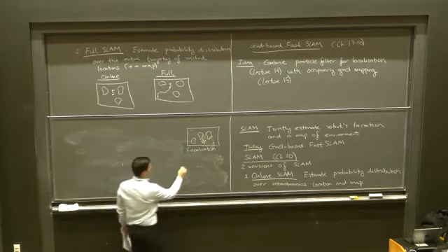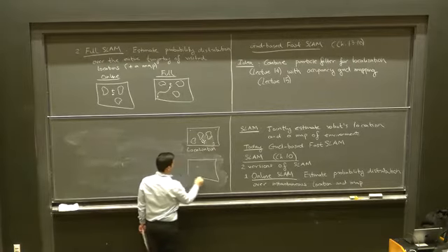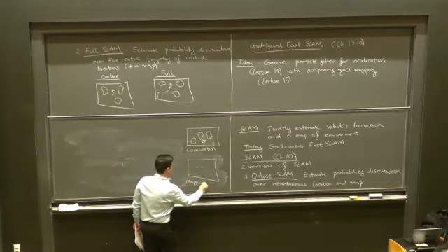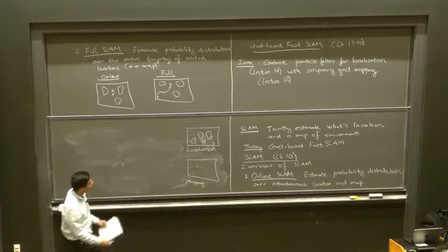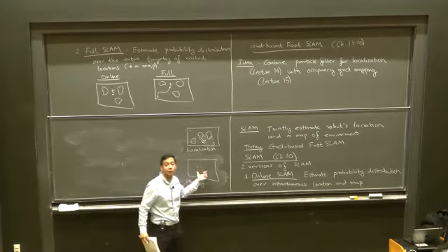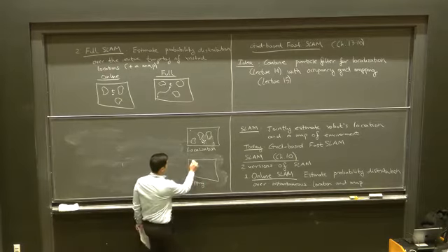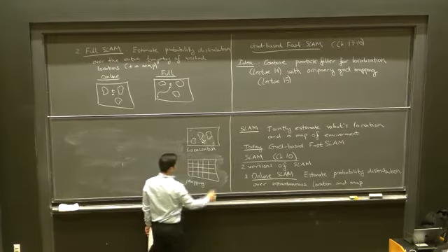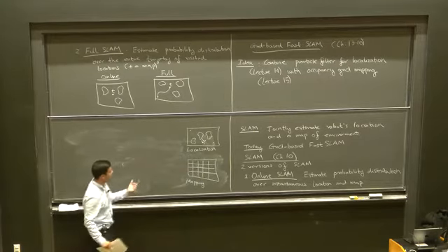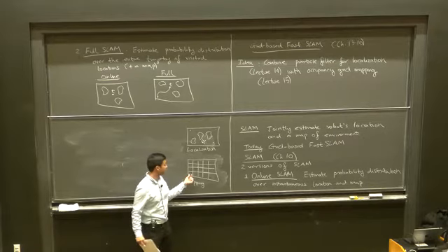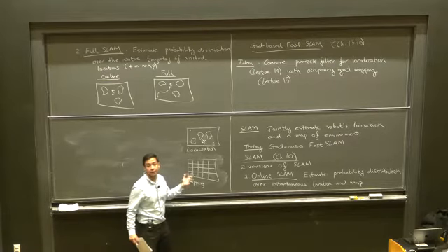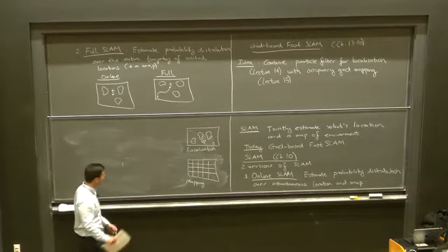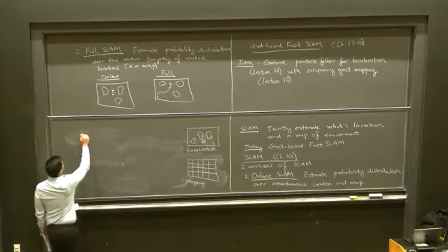For mapping, in the previous lecture, I guess this is slightly harder to draw, but we were maintaining a belief over maps, right? And the way we did that with an occupancy grid map was that we had some probability associated with each cell being occupied or not, and then we updated those probabilities as the robot moved around and collected more measurements. So with SLAM,